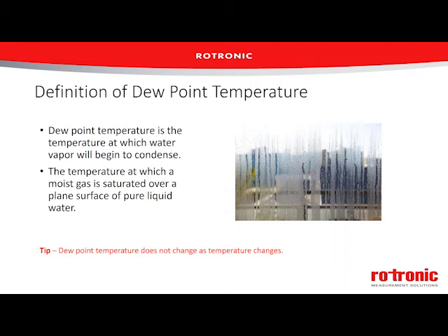And if we take that a little bit more technically, it's the temperature at which a moist gas is saturated. So it's got as much water vapor as it can hold. So fully saturated over a surface of pure liquid water. And it's important that we're over top of pure liquid water because that's what drives the partial pressures and the saturation vapor pressures, which determine how much moisture can be held in that space. So dew point temperature is simply the temperature at which we've got a saturated gas over water.